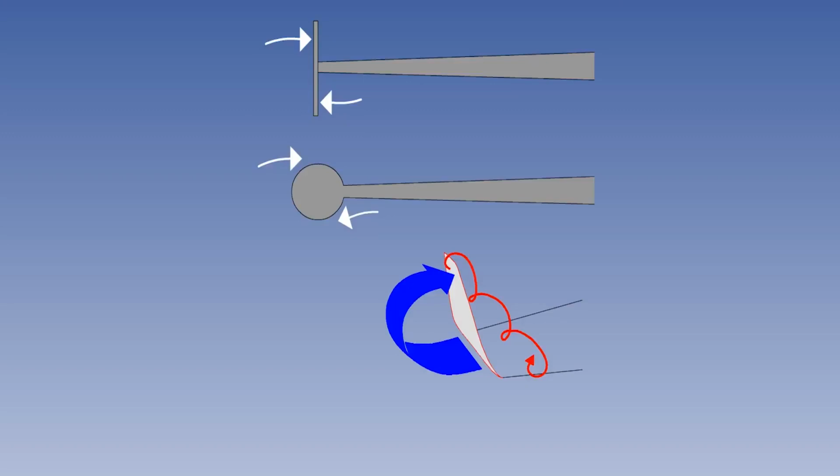Probably the most widely seen method of controlling wingtip vortices is the winglet, which is now incorporated into many categories of aircraft, large and small. Small vertical or near vertical extensions of the wingtip are shaped and angled to the induced airflow, generating a small forward force, or negative drag. Winglets also partly block the flow of air from lower to upper surfaces, reducing the tip vortex strength.